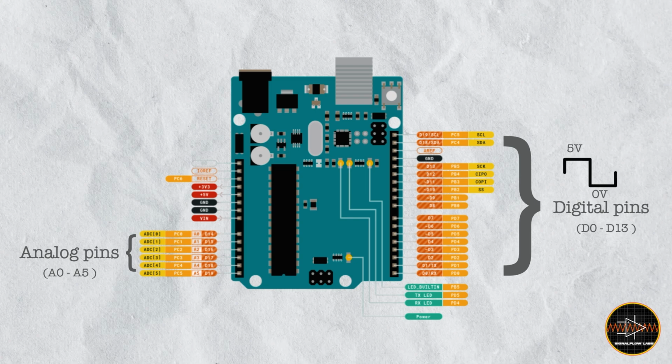They can even take digital input as well. As compared to analog pins, these pins can take digital input as well. They can take input as well as give output. So digital pins can do both things. They take input from 0 to 5, detect it and give it. There is a threshold voltage: let's say if it's above 2.5 volts, it detects a digital yes. If it's below 2.5 volt, it detects a digital no. And that way you can do it.